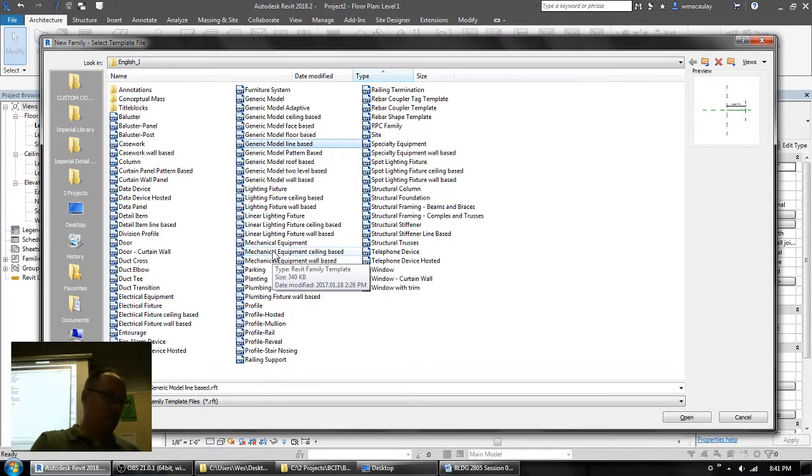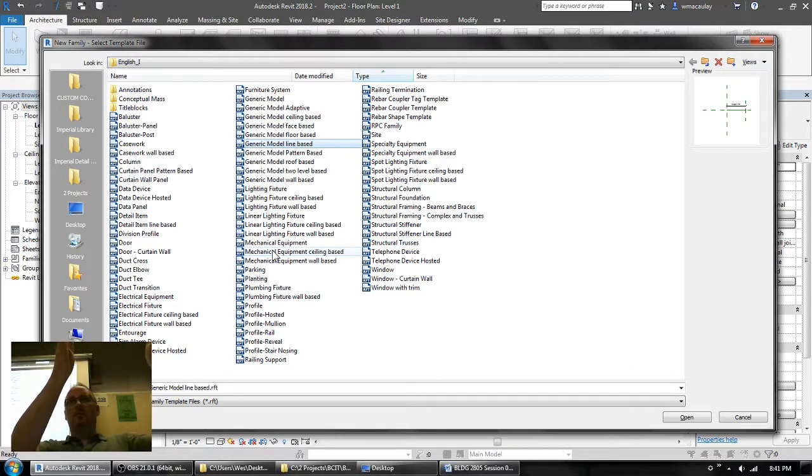So it might be parking stalls, it might be chairs, it might be a filler panel on some millwork. So you've got 16-inch cabinets in this opening. You got 3.5 inches left. What are you going to do? Well, you can make a 2-pick family that builds a little extrusion into that gap and fills it in, and your millwork trade would provide that for you.